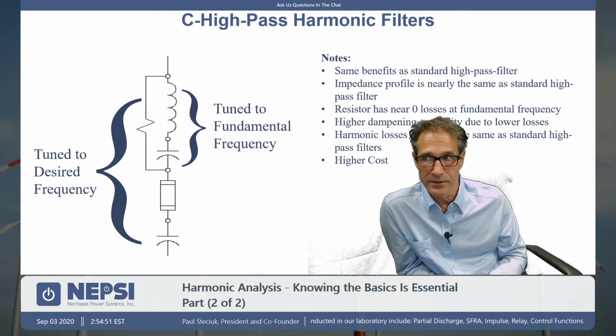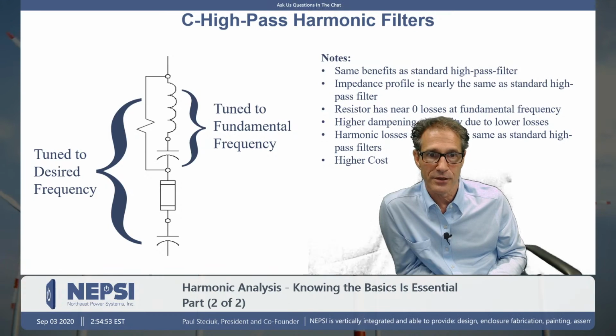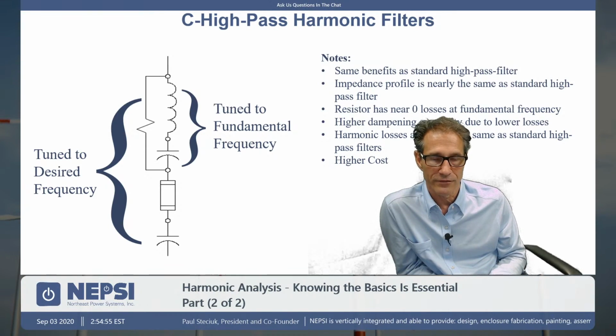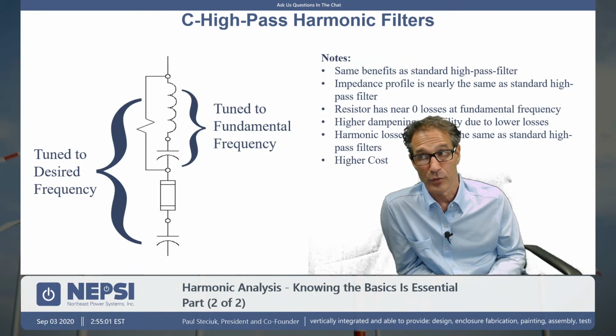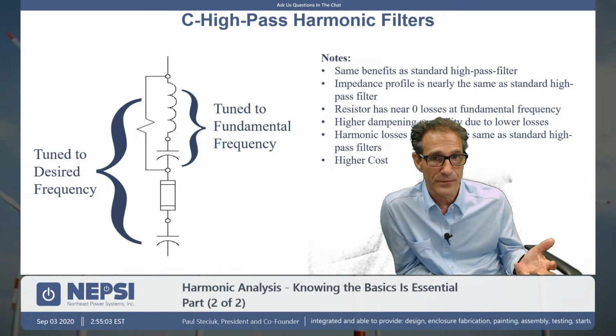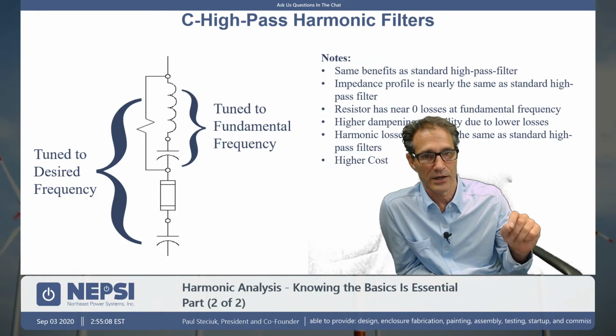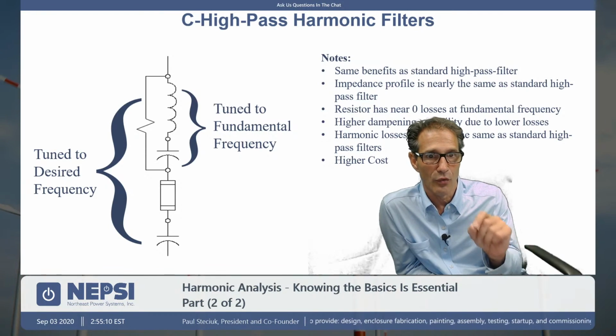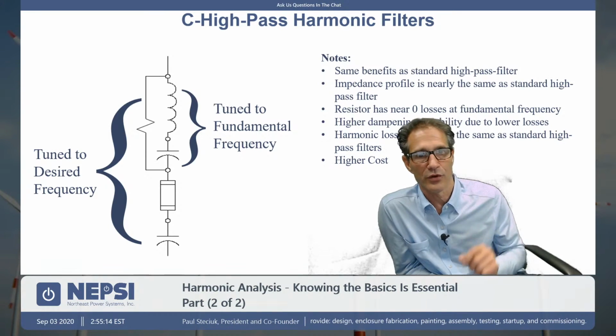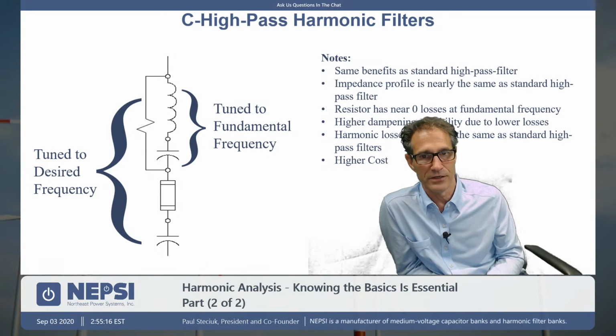But with that being said, for arc furnace applications, we will often see third harmonic filters. Cycle converter applications, we will see third harmonic filters. So remember, if you have resonance and it's a third harmonic, it can be a positive sequence third harmonic on a system. Very low levels of third harmonic, even if they exist, if we have a third harmonic resonance, could potentially be an issue.